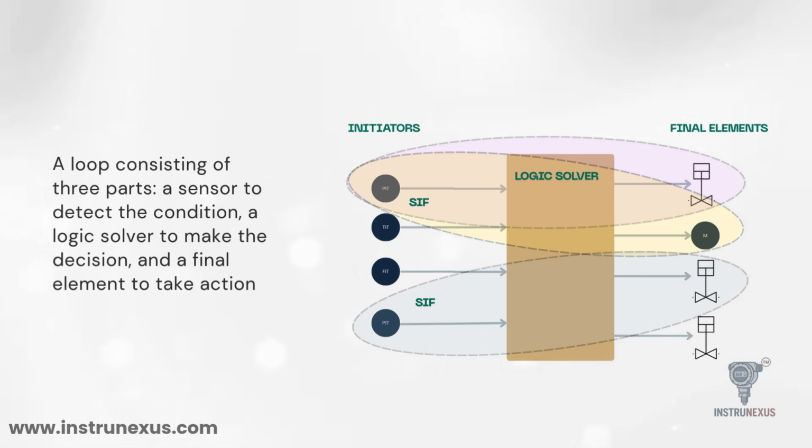Let's look at the distinction between a SIF and the Safety Instrumented System, or SIS. The SIS is the entire bundle of hardware and software. The SIF is the function inside that system. A single SIS logic solver might host dozens of different SIFs.